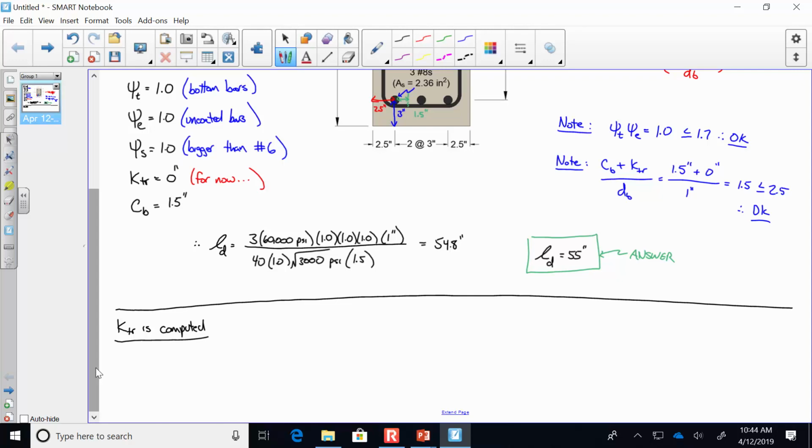Well, I'd argue for typical beams, like you're talking about a beam that would have 3 number 4s. And I'm saying that beams typically don't have 3 number 4s. That is a really small amount of reinforcement that you just don't see in a beam. If you have a beam that's 20 foot long that only has 3 number 4s in it, I'd like to see how big that beam is. Because that beam is probably tiny and isn't seeing any load and might crack under its own self-weight. That's a very light amount of reinforcement. And so I just don't think practically that it would happen, okay?